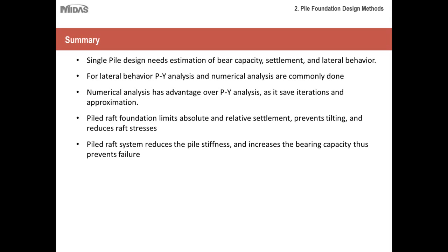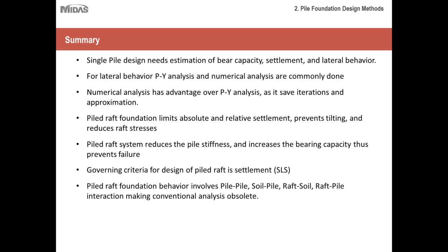Pile raft foundation reduces the pile stiffness and increases the bearing capacity and thus prevents the uprooting failure, where the complete pile system is mobilized. The governing criteria for the design of pile raft is the settlement or SLS.